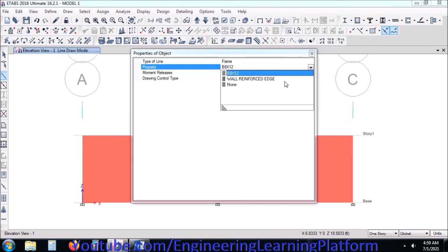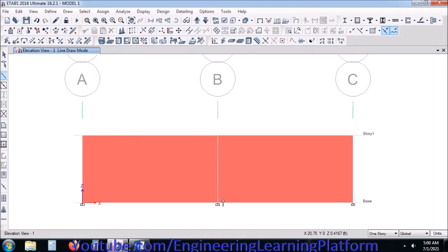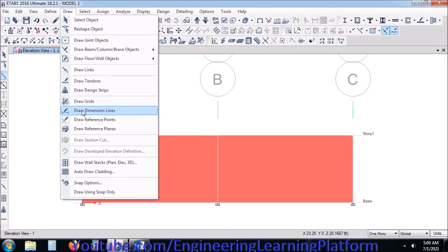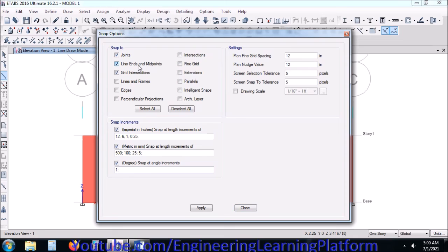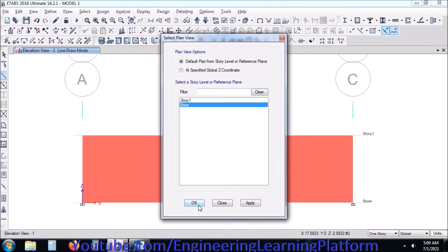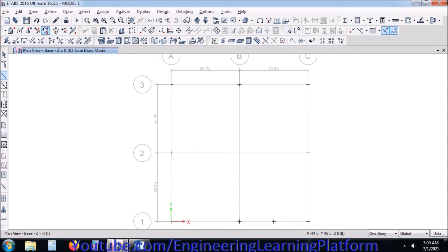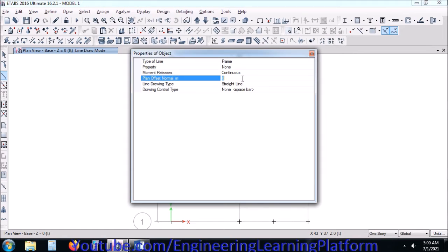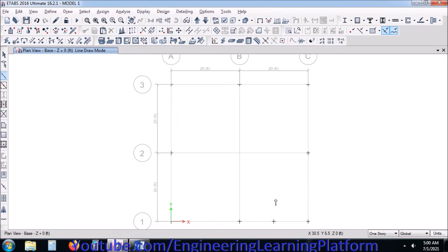Now let's draw the openings in the walls. Actually, we should have drawn the openings in the walls and completed the model in a previous stage, but let's just try to do it, as I just have to see that the model we have done so far is right. And for demonstration purposes, the structural behavior will not change much as it's a masonry structure. So if we add openings along with the lintel and the spandrel and the tie beams along with the band beams, the behavior of the structure will not change much. However, the stresses in the structure will reduce the more corner elements we add.